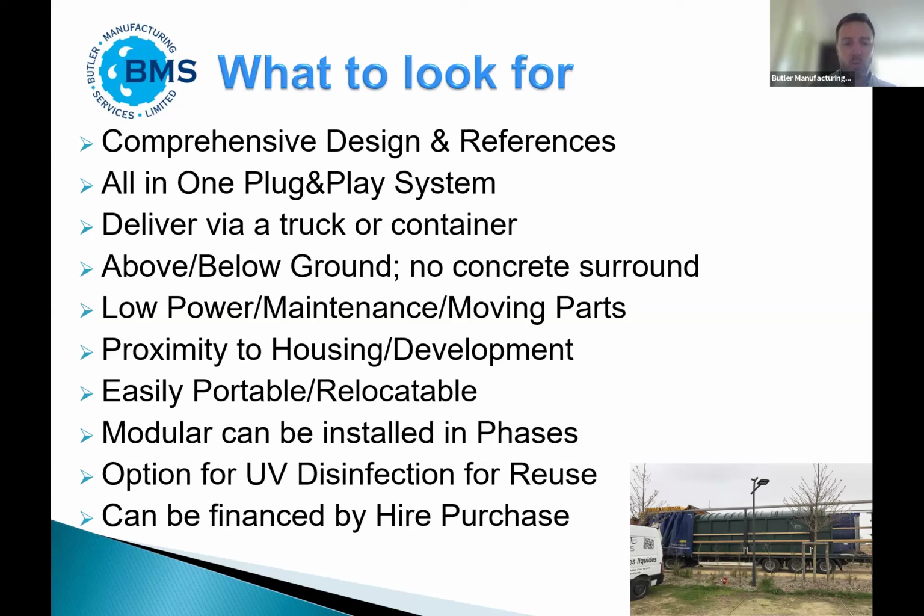Then, how close it is going to be to a housing development. Typically, you're looking at a setback of about 50 meters, but with temporary sewage treatment, a very close area to the housing is often required. For example, we have a housing estate in Eden Derry where the setback is only 5 to 10 meters. I can show you later on, but the solution was there: an enclosed packaged sewage treatment plant in a Steeltech-type shed, which allows development to go ahead.